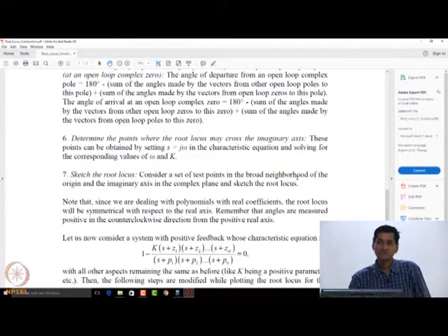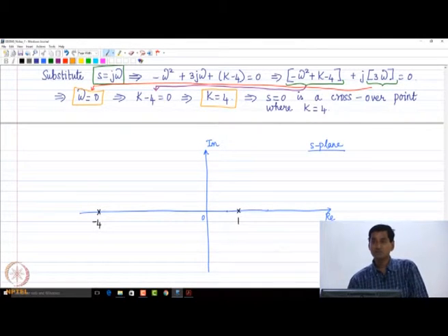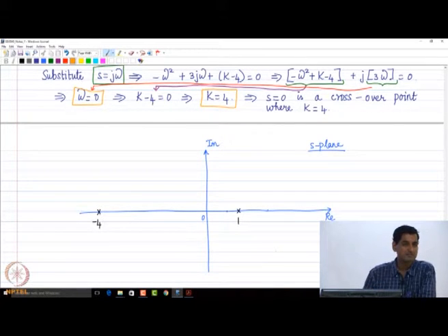So, for example, if you use software like MATLAB, you can pretty easily get the actual root locus, but here we will just use steps 1 to 6 to plot the root locus. Okay, is it clear? And once again, please use the rlocus command in MATLAB to sketch the root locus for all the problems that we are doing. Even in homework number 2 which I have given you, you need to construct root locus for certain problems. Sketch by hand and then check your solutions by plotting the root locus in MATLAB, right. So, let's construct it based on whatever we have learnt.